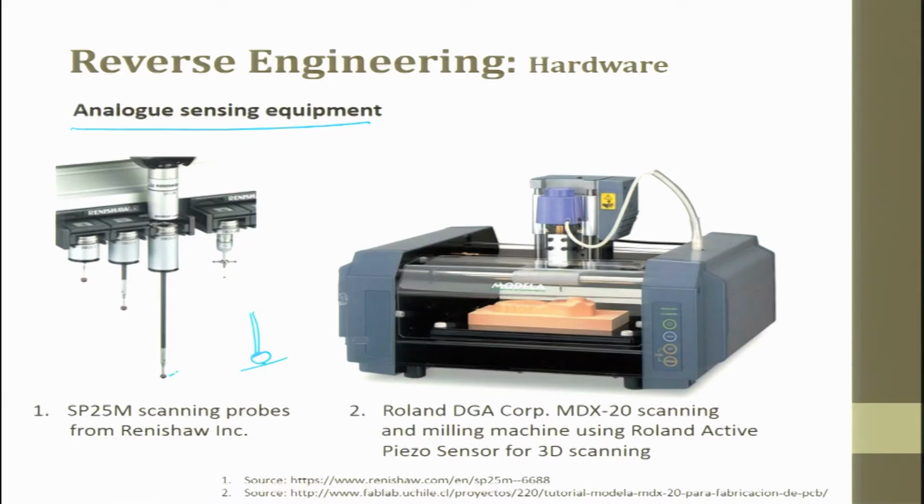So, you can see here the tip of the CMM is made out of ruby. Ruby is nothing but alumina. So, this alumina, when it touches a surface, this is a probe which touches, and here you will have a connector circuit breaker or a contact breaker which tries to break the circuit, and you try to get the data. So, you can see here different types, a long probe, a short slender probe, a star type probe. You can choose which one you want for your requirements, and then you can start using it.